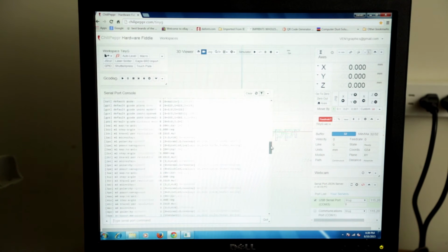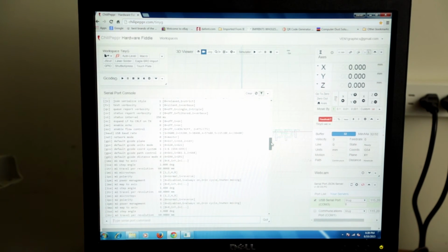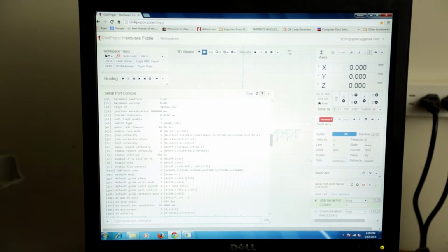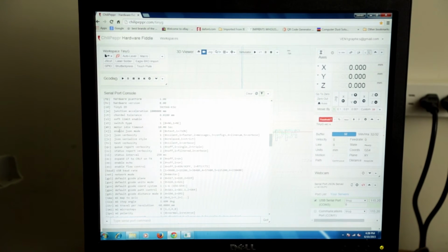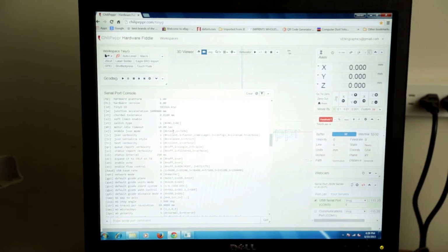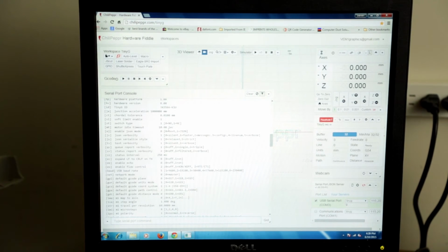All right. Switches. It starts off at switches and stuff. Now there are 2 different modes that you can program this in. One is JSON code, and one is text mode. Right here, we're setting up for enable in text mode. If you get further advanced and you want to do it in JSON, it's like curly brackets in code with commas and stuff. You would type equals 1. So it'd be $EJ equals 1 to be JSON. $EJ equals 0 is text mode. Okay, so we're in text mode.